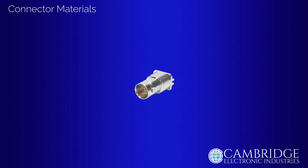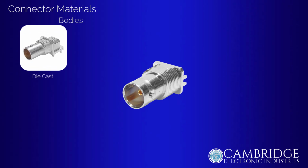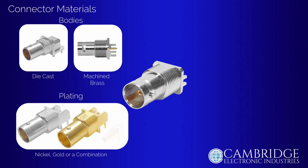Cambridge Electronic Industries coaxial connectors are designed and manufactured to provide a durable and reliable connection using high-quality materials across all component parts. Connector bodies are manufactured from either die-cast zinc or machined brass. The body is then plated with nickel or gold, or a combination of both. While there is no electrical difference between these finishes, nickel plating provides a cost-effective, corrosion-resistant, hard-wearing coating with an appealing silver appearance.